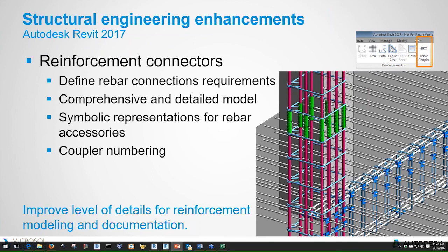You can use schematic connectors to define requirements. Detailers can use them to produce shop drawings. Manufacturers can go into full detail, precisely modeling and representing reinforcement connectors. And also you can create installation instructions with these. Okay, you can add connectors to groups, assemblies, and partitions, and also they have unique coupler numbering and annotation formats that you can use to either illustrate your design or export to other formats.